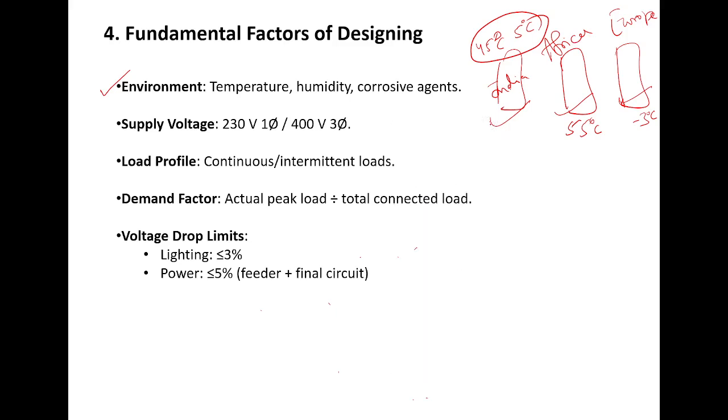If I am selecting a cable, which insulation material will be used, whether PVC or XLPE? If I use PVC in Europe, it will crack in this cold temperature. So by keeping all these things in mind, I will select my equipment.